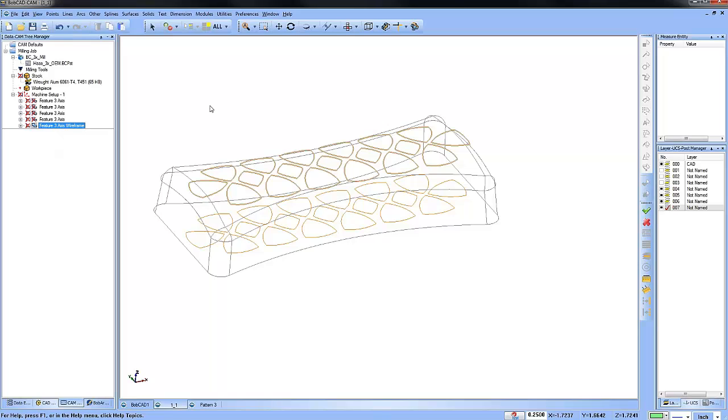What about cutting the stock around the pattern? Can you trace in BobCAD to vectorize? If you have BobART, you can trace images and vectorize them. And then as far as the boundary, you could create offsets and project that down to do a pocketing routine or something like that with your projected geometry. So that's how you would do raised or lower in that type of scenario.